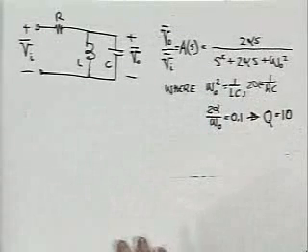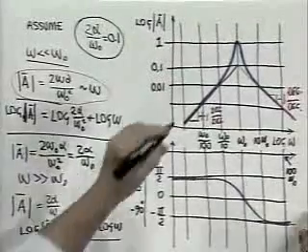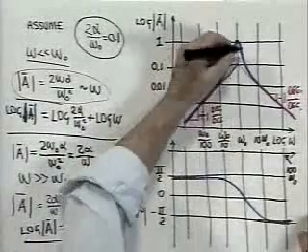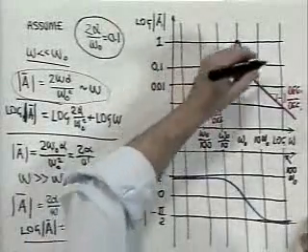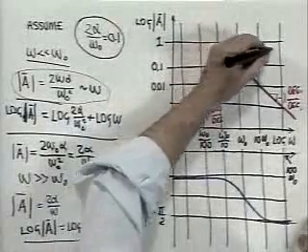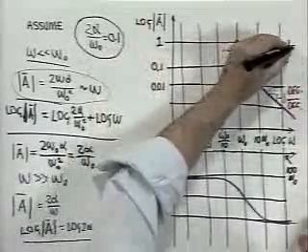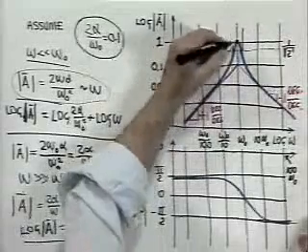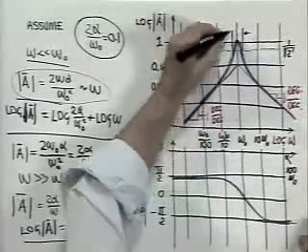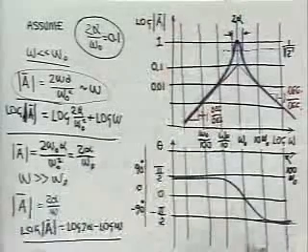And knowing what we know about resonance in circuits such as this, I could plot up here the half power point, which, rather than being at 1, is at 1 over the square root of 2. At that point, this curve is just 2 alpha in width.